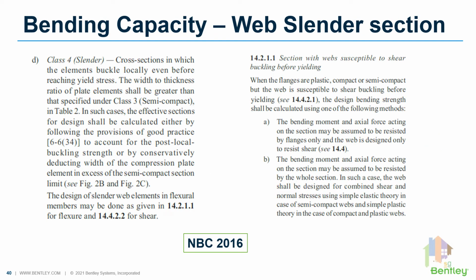IS800 code doesn't clarify about this, though NBC code suggests to consider the web buckling criteria for web slender section design. We have been discussing with the code committee for clarification of the design rules for bending capacity calculation of web slender section. Meanwhile, it is implemented in STAAD with help of other international design codes.